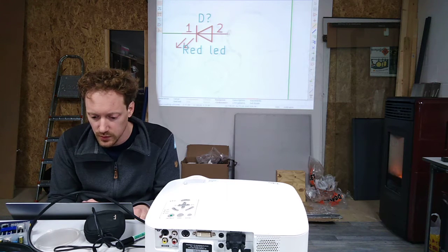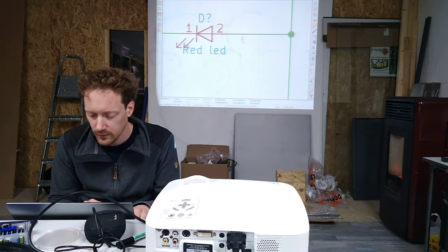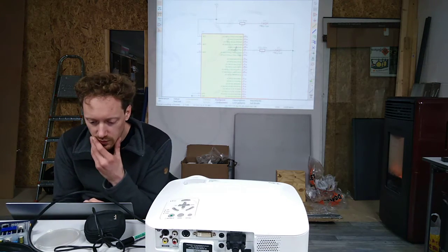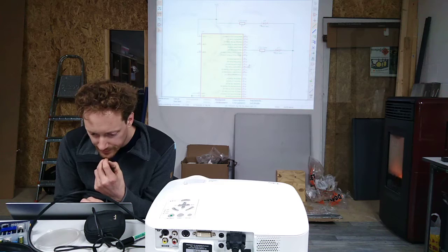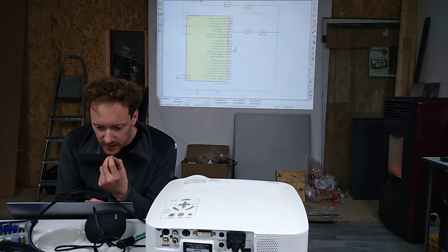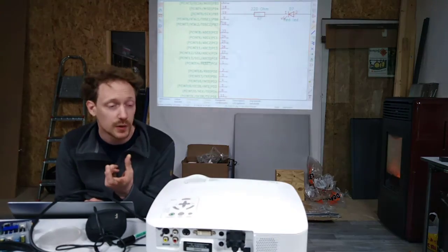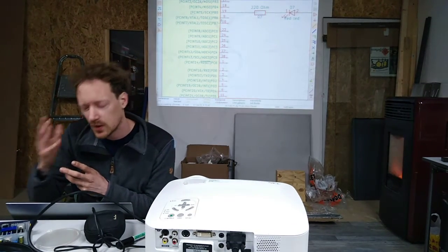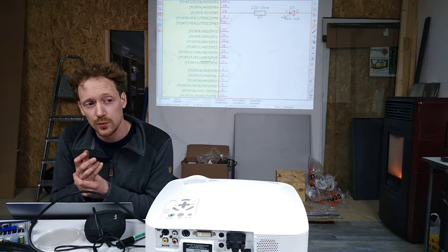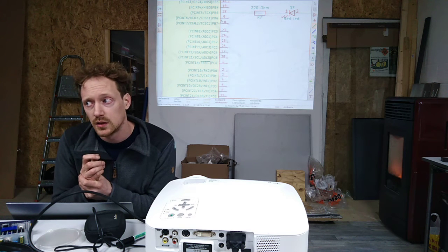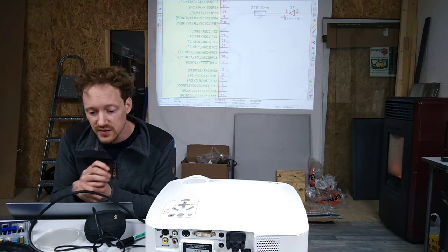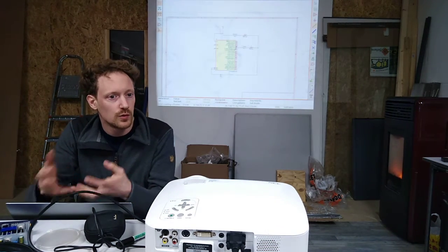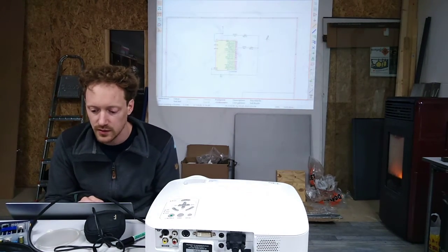So we connect this one as well. Well, and we can continue to do so. For example, the pins 9 and 10 need to be connected to a crystal. The crystal needs to be connected to, I think, 22 picofarad capacitors, and this is essentially what you do when you're creating the schematic.